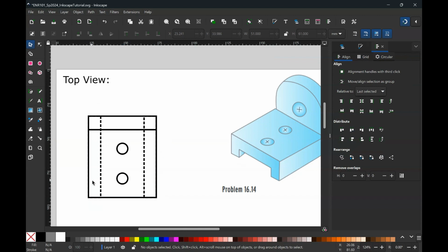they are features that are relevant to this top view. We can also include the presence of this hole by placing another dashed feature. In this case, this hole is a little larger than the 8 millimeters across that we set. So let's make this 12 millimeters across.